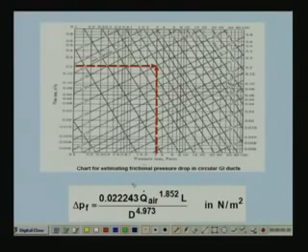As I was telling, once you know the flow rate Q dot, and once you know the dimensions, because as I said, Q dot is equal to A into velocity. So velocity is known, Q dot is known. So first find out A. Once you know A, you can find out D. So D is also known to us, Q dot is also known to us. So we can find out the frictional pressure drop using this equation, which I have discussed in the last lecture.